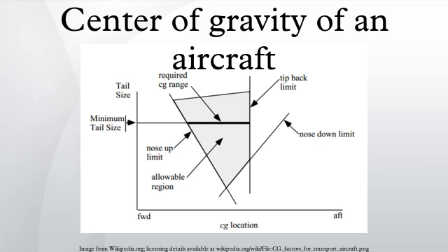Incorrect weight and balance in fixed-wing aircraft. When the center of gravity or weight of an aircraft is outside the acceptable range, the aircraft may not be able to sustain flight, or it may be impossible to maintain the aircraft in level flight in some or all circumstances. Placing the CG or weight of an aircraft outside the allowed range can lead to an unavoidable crash of the aircraft.